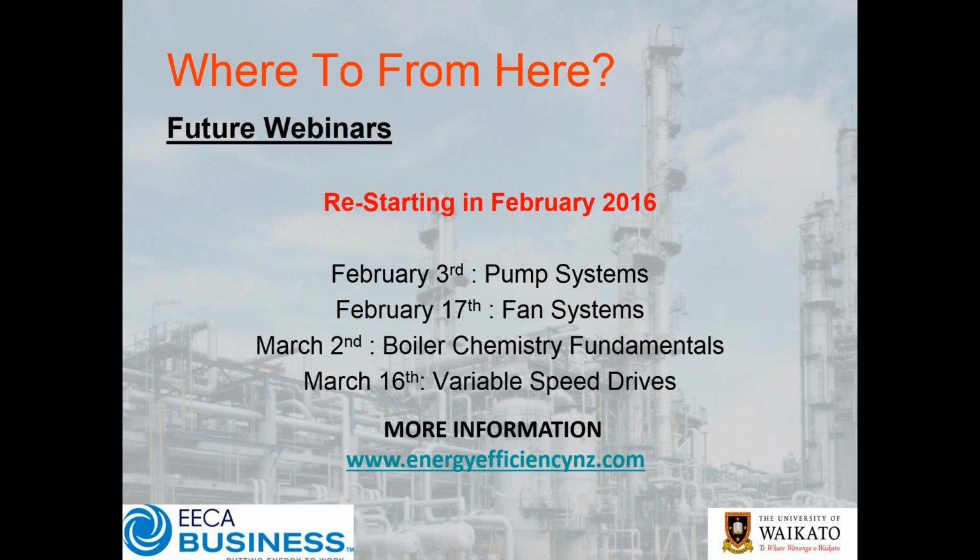I haven't, but what you're saying makes good sense. And in principle, this is a really good example of when we talk about peak load management and demand management. This is the next level up, where you deal with your leaks and all your other wastages, and then you look at where the air's being used, and that's where it's back to the business case. You'd have to look and say, well, my demand is currently this. If I switch to this other nozzle, is it more efficient?